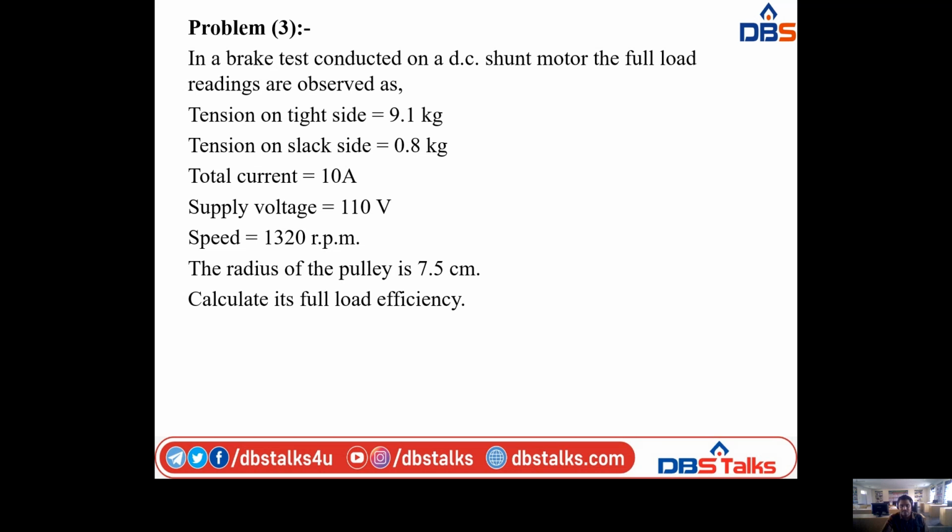Find the efficiency of the machine when running as a motor taking a current of 25 amperes on a supply of 250 volts. The resistance of its armature is 0.3 ohms, and that of its field winding is 200 ohms.